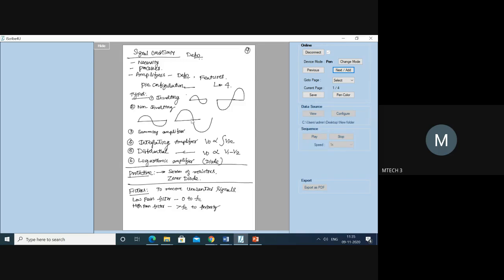Okay. Then the next, third one. Band pass filter, sir. Band pass. Okay. What does this band pass do? It allows all the frequencies within a certain band, sir. Yes, it allows the frequencies within a certain band. That means FC1 to FC2 is allowed. Correct? Yes or no? Less than FC1 is not allowed, and greater than FC2 is also not allowed.